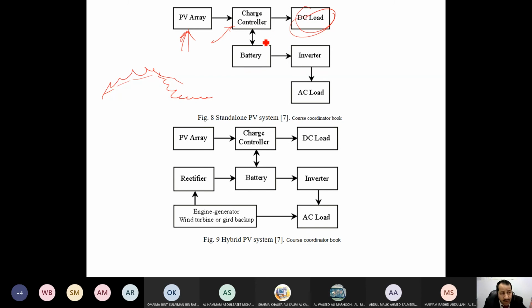The same thing could be said when we charge the battery. It's not preferable to charge the battery with variable voltage, power, current. No, it's preferable to be constant because this affects the life of the battery. It may die early. So to make it work for a long period of time, we need to make sure how we charge them. The way of charging, the way of discharging itself also affects the life of the battery.